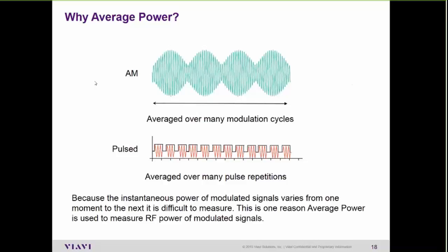Again, with some signals, you want to look at peak power or pulse power. GSM is the only modulation format that I know where you really measure a peak power when setting power, because it is time slot based. It's not continuously being transmitted. One user gets, say, time slot 1 and time slot 4, and so the signal is off the other periods of time. So you're basically looking at just a peak power for that particular measurement.